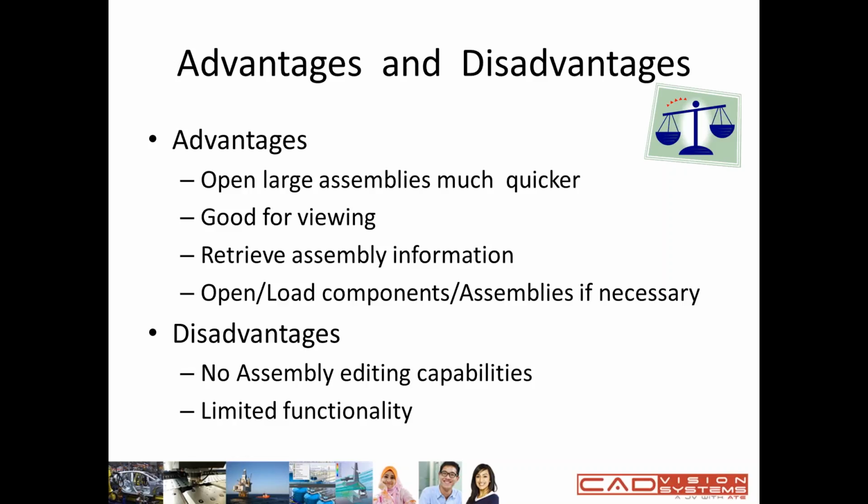In Large Assembly Mode, it took me 37 seconds to open it. While in Large Design Review, it only took me about 13 seconds to open. So it basically reduced from the full resolve of 180 seconds to 13 seconds. It's basically less than a quarter. So it will save you a lot of time when you open to view it.